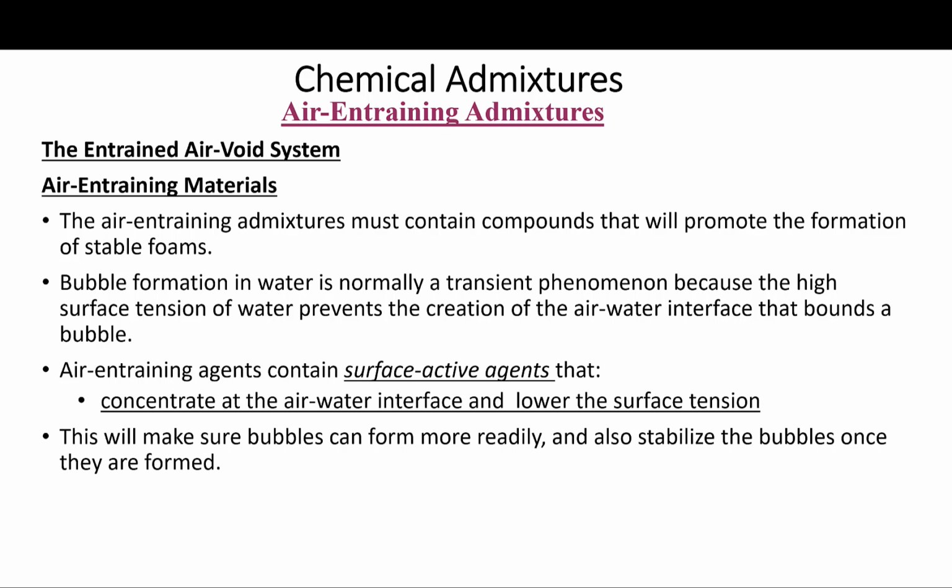So air-entraining agents contain surface active agents that concentrate at the air-water interface. They lower the surface tension so that bubbles can form more readily and stabilize the bubbles once they are formed. All right?